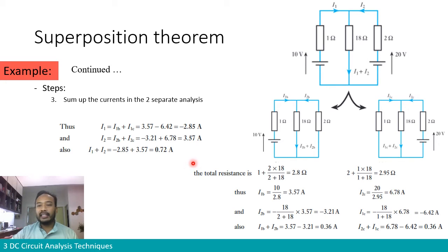So you see, the analysis is now simplified by considering the sources separately, and later we just sum up the two results together. In comparison to, for example, mesh loop analysis, you need to go through KVL, and there is the branch in the middle where you should consider the current in this loop and the current in that loop. Usually students might make an error.